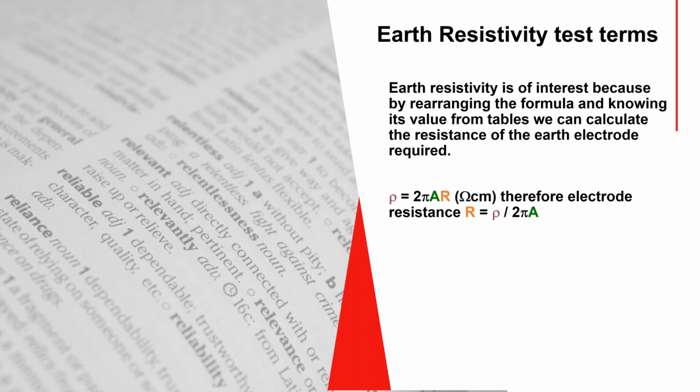And the important thing here is that you can get software from the companies that sell grounding materials, like Lincoln or Hubbell Lightning Protection. Companies like that typically will provide you with software, and you can plug in this relevant data, like the R number that you're trying to achieve, and also your soil resistivity for your local site.